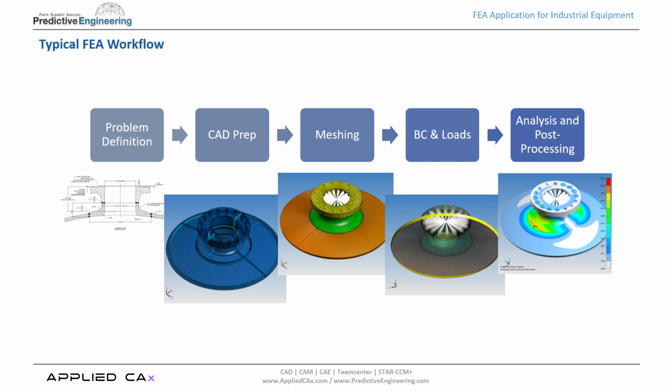Finally, we run the analysis using SimCenter Nastran. Results such as stress, deformation, and fatigue life are extracted and compared against ASME or client-defined limits to validate structural integrity.